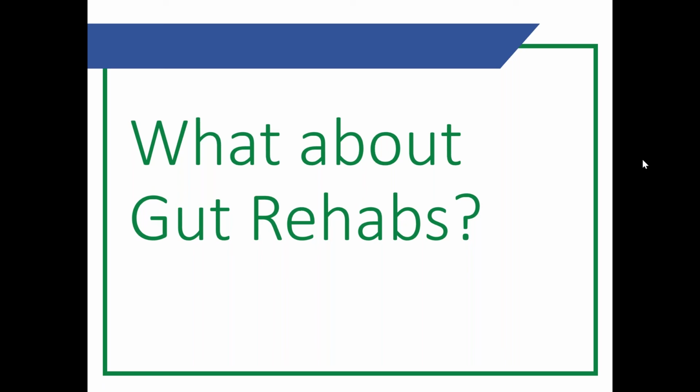But LEED v4.1, should it get adopted as it currently stands, has for the most part said that for most of this checklist, you can ignore a majority of it if there's not a problem that's visually apparent as far as moisture issues go. So there's no reason to dig up the slab and fix some of these issues, or to slope the house on an existing home if there isn't an apparent moisture problem.